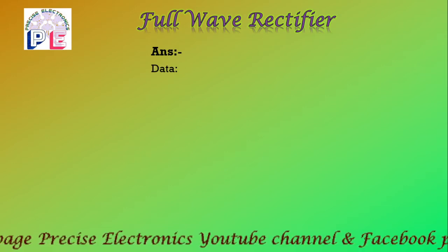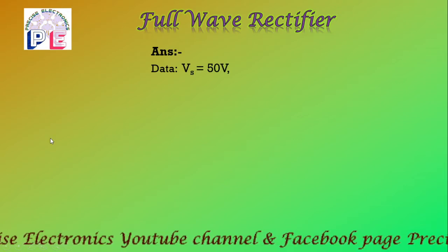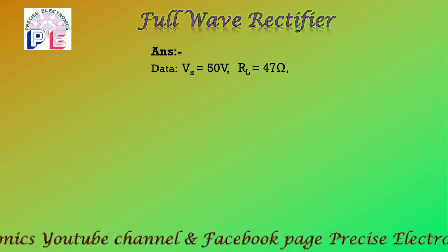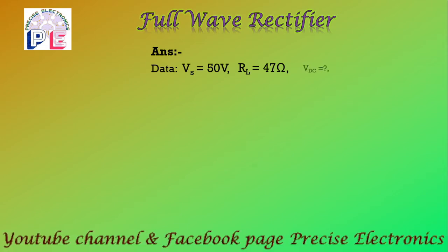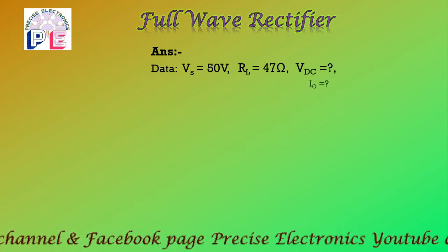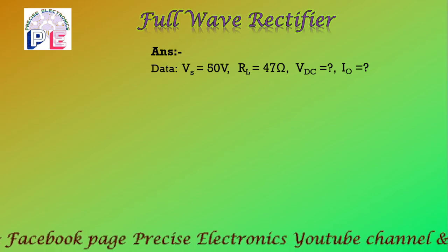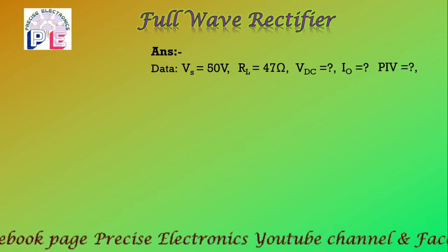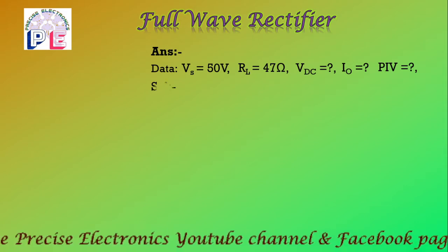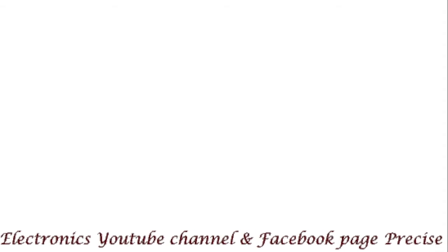Data. What is data? Vs secondary voltage is given, that is 50 volt. Next, RL is given, that is 47 ohm. We have to find out VDC, that is average voltage, load voltage, output voltage. Then IO, current rating of diode, and PIV of diode used in this circuit. So now we are going to solve the numerical.